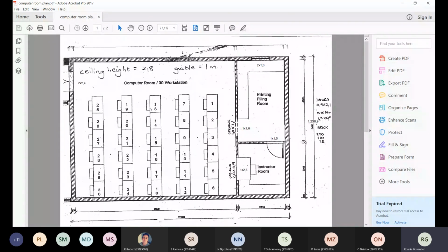The external walls are all double skin. The double skin has face brick on the outside, and it's going to have cement bricks on the inside. So I worked out all the brickwork from the outside, including the gable that you'll get here for the roof. And I took away the opening for the double door there, and I took away the opening for the window there, right?